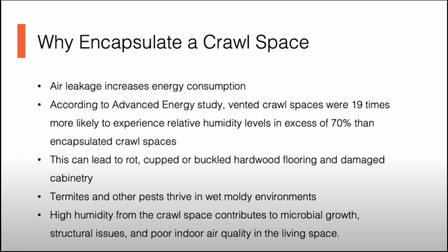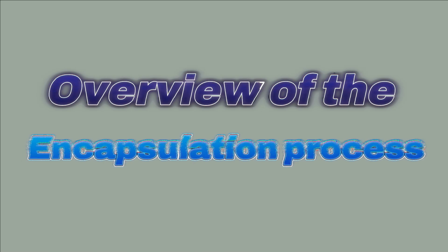These high humidity conditions allow termites and other insects to thrive, while also providing conditions conducive to microbial growth. Other issues with these high humidity conditions include the potential for structural issues and poor air quality in the living spaces. As you're seeing, there are a lot of reasons to not have vented crawlspaces. As we've become more advanced in the construction and pest control industries, we've figured out that encapsulated crawlspaces are a great solution. Overview of the encapsulation process.